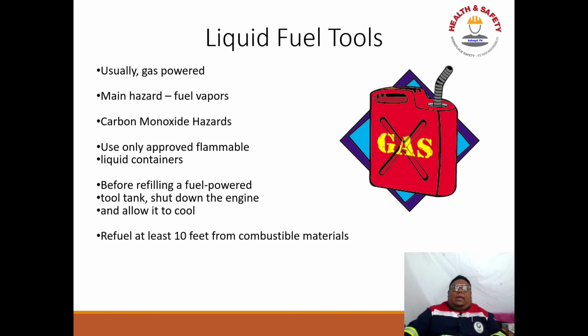Use only approved flammable liquid containers. Before refilling fuel powered tools, shut down the engine, allow it to cool, and refuel at least away from combustible materials.